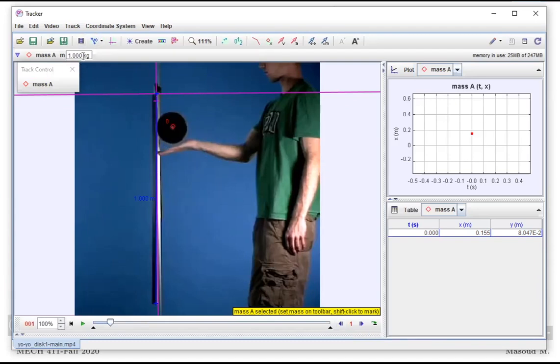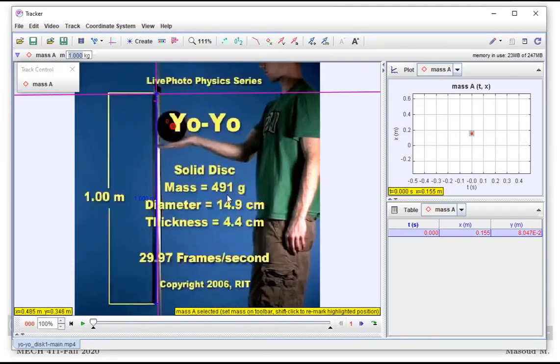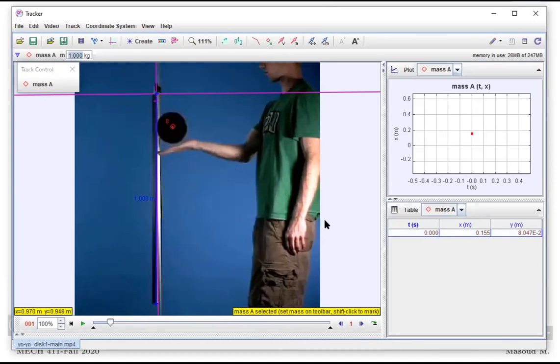Right? If you wanted to do analysis in the software, we could also say how heavy that mass is, but for most of our analysis, we only take the displacement out of this software. We don't do further analysis within the software, which has the capabilities. So just leave it as 1 kilogram. We don't even have to modify. If you want, we can just put the value of the mass from the given number, like 491 grams. Right? I'll just leave it as 1 kilogram.